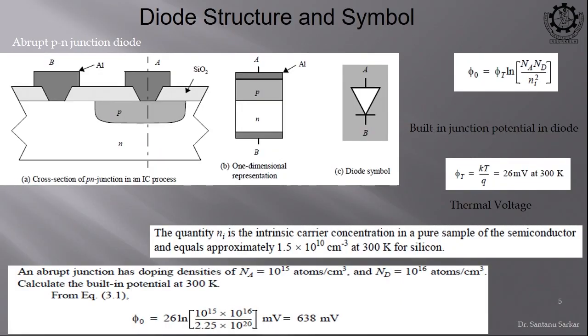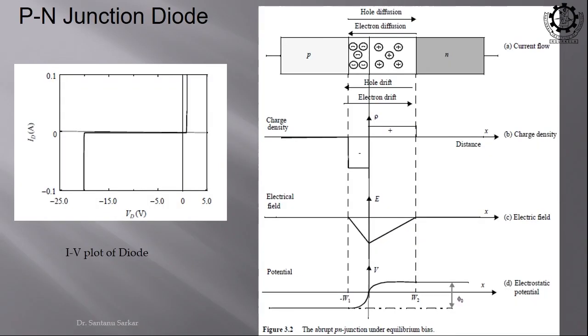Okay. And this is our diode structure. We have P type material and N type material, anode and cathode, and this is our device structure. This is our P material, this is our N material, and these are our contacts. The contact is just like we discussed, the metal deposition and contacts, the same thing is there, and in between we can have a barrier, that is SiO2.